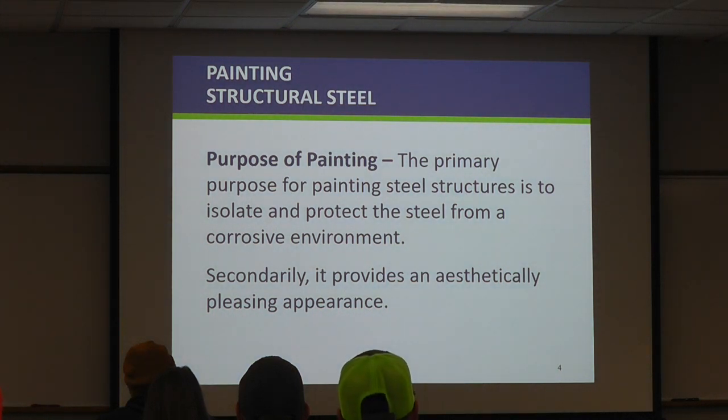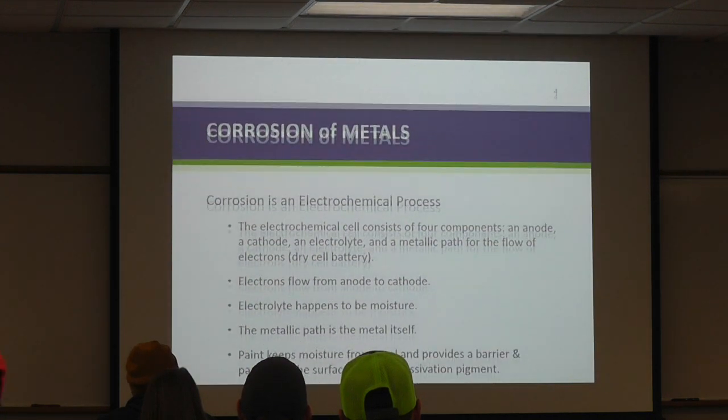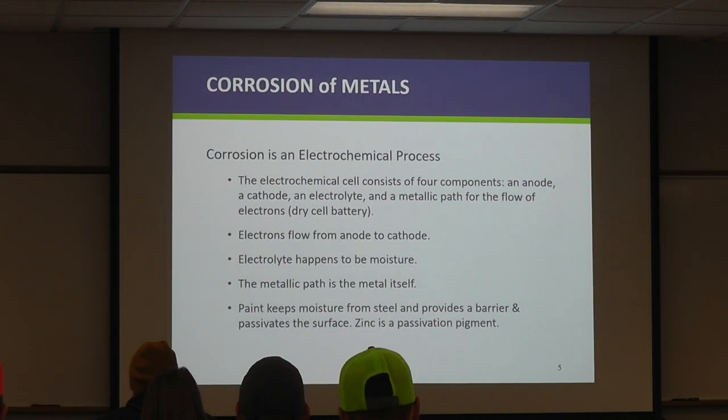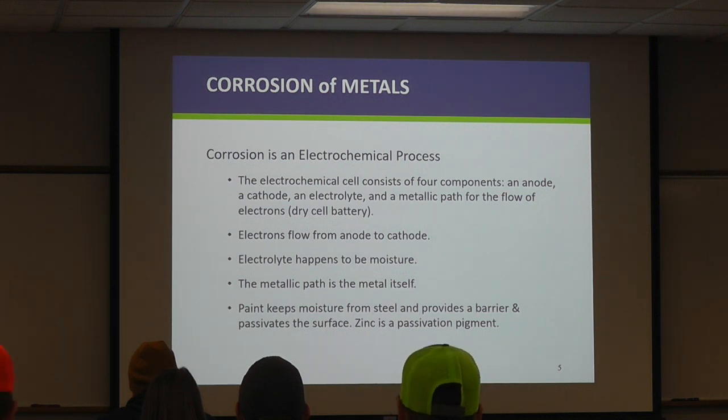So the whole purpose, right, is to isolate and protect the steel from our very naturally corrosive environment. It also provides an aesthetically pleasing appearance, especially if you're in larger communities. They like things to look very pretty. Think of corrosion as an electrochemical process. You've got an anode, cathode, and an electrolyte, a metallic path to follow. It's kind of like a dry cell battery. Our environment, combined with the very wet environments, as well as